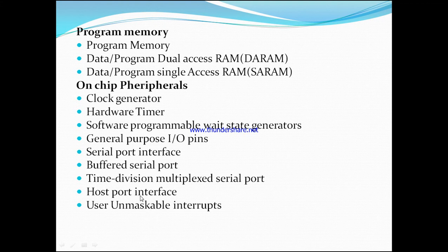Next one, host port interface. It is an 8-bit parallel port used to interface a host device or host processor to the C5X. Information is exchanged between the C5X and the host device through on-chip memory. User maskable interrupts.